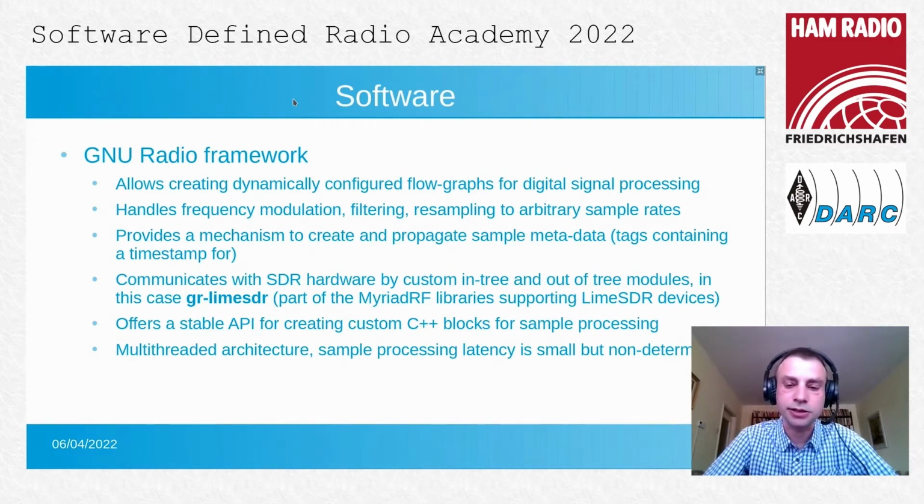non-deterministic sample processing latency. And this is important because usually we cannot determine at which exact time our samples will be transmitted by the software-defined radio. So we actually need the crucial mechanism of associating timestamp tags to each sample.